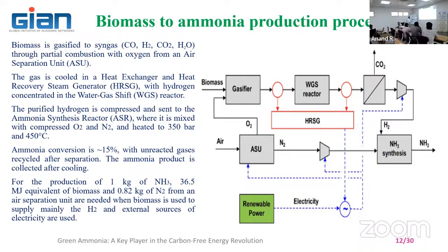You can supply it to the steel plant. Activated carbon has several applications: wastewater treatment, many things. Activated carbon can also be a catalyst for the same process itself. What we did is convert the solid particles coming out of the gasification, the activated carbon, into a metal-impregnated carbon. We can convert it to a catalyst, which can be used in the gasifier system itself to reduce the activation energy of the process.